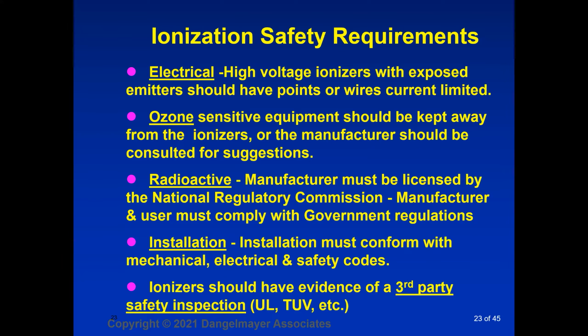One thing I would mention, you've all heard about CE marks, I'm sure. These are inspection marks that are used in Europe for products that are acceptable there. The thing to remember about CE marks is that a CE mark is a self-certification. You don't have to go to a third party to put a CE mark on your product. It's very nice to have that CE mark, but if it could pass CE, the requirements are the same for the safety organizations. So why not turn it over to a third party to do the safety inspection for you? Always look for those safety inspection stickers.